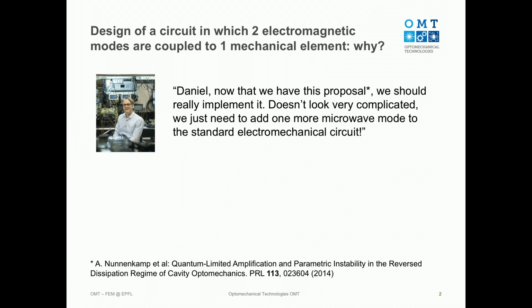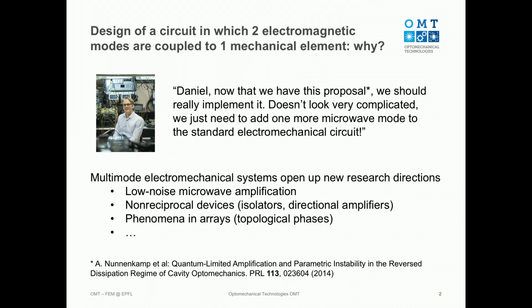Okay, so this is the plot I extracted yesterday. Maybe it's a little bit deceiving intentionally, but this is the point that now I'm looking at the lower frequency mode for the entire circuit. I look at the charge distribution, and I see that charges are here. So this creates this capacitive coupling to the feed line. It's not that much, so I think it's about two orders of magnitude less than the charge on the capacitor, which is of course expected. But this is enough to change your resonance frequency as well as your coupling rate.